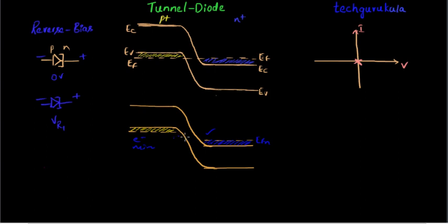When you consider the junction width, even though you reverse biased it, the junction width increase will be very negligible. So even then the depletion width will be in terms of angstroms, and there are empty states at the other side where the electrons can tunnel through instead of surmounting the barrier. So these electrons will tunnel through and there will be a current flow. Unlike other diodes, which in reverse bias don't allow current flow, tunnel diodes do allow it.